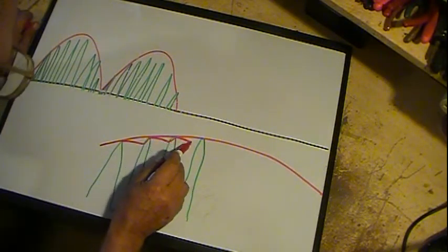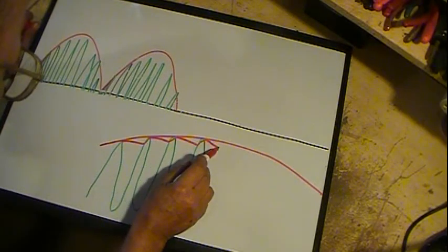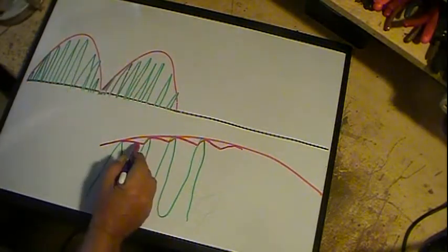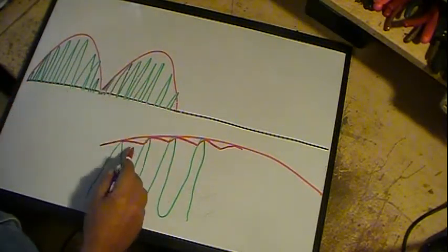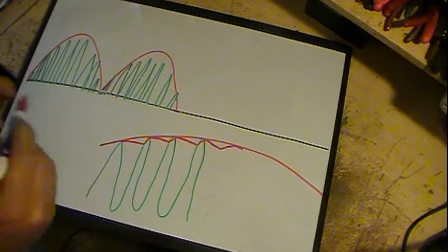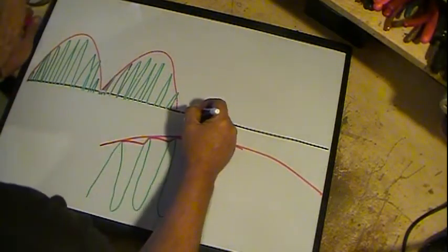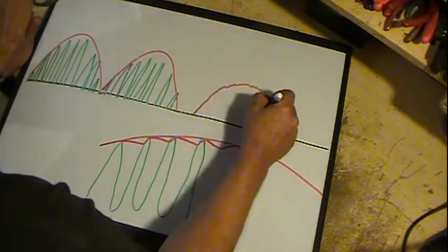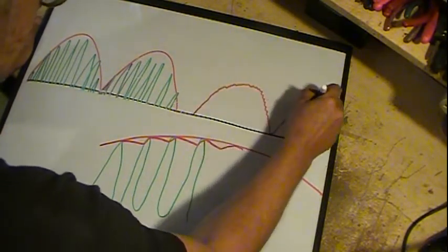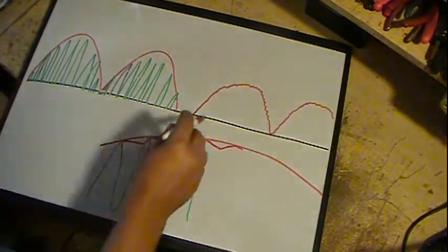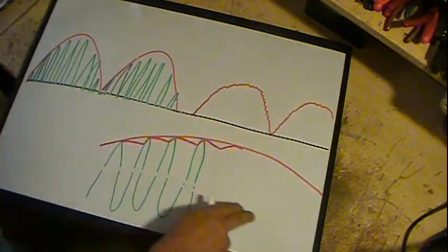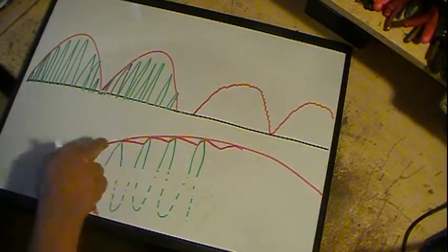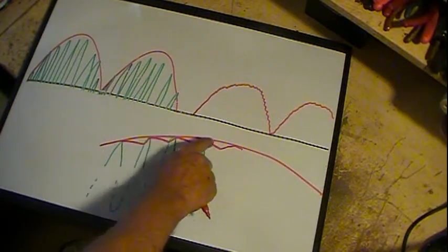It recharges, and then it drains off, and up, and drains off, and it just keeps doing that. Depending on how good the filter is will depend on how much of what is known as ripple is in here. But you end up with a signal that will have a little ripple in it coming out, and I've gotten rid of this here because this is what's charging the cap up, and I end up with just this little ripple.